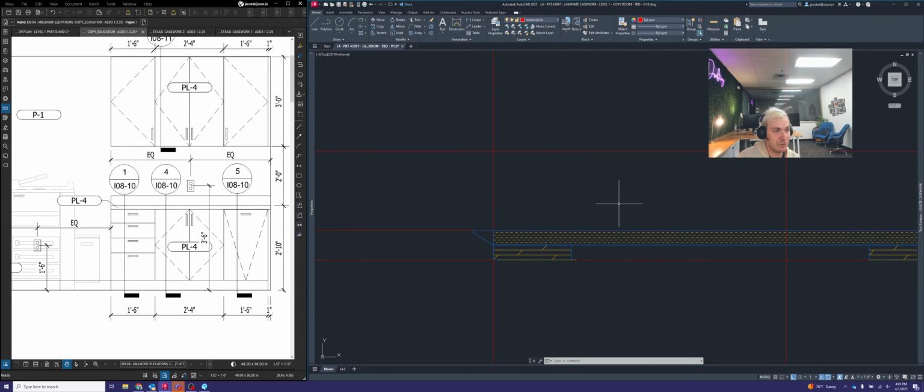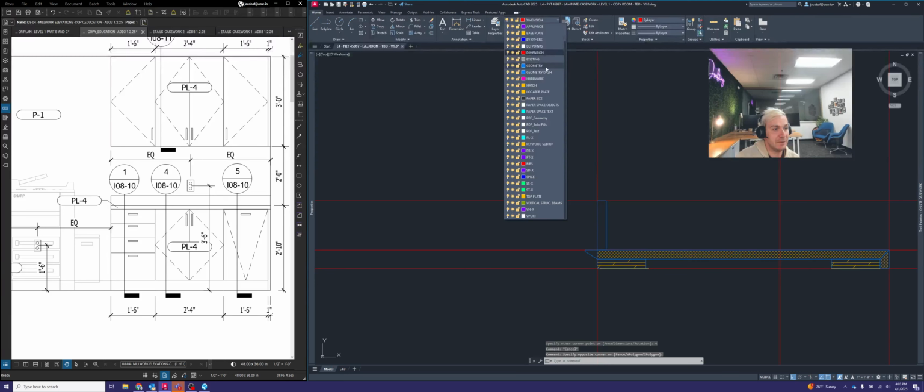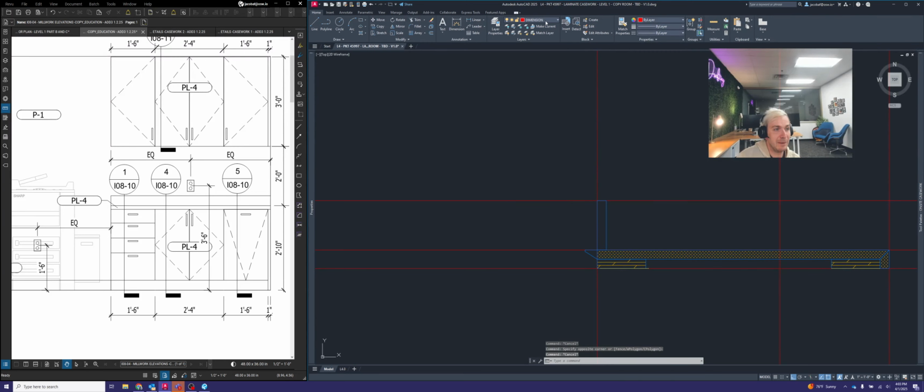We're also going to drop in a backsplash here, which will be the same material as the countertop. So we're going to model that here at 0.75 or 3/4 of an inch thick by 4 inches tall. So make sure this is on the geometry layer. And again, I should probably actually switch that back so I'm on that layer permanently.